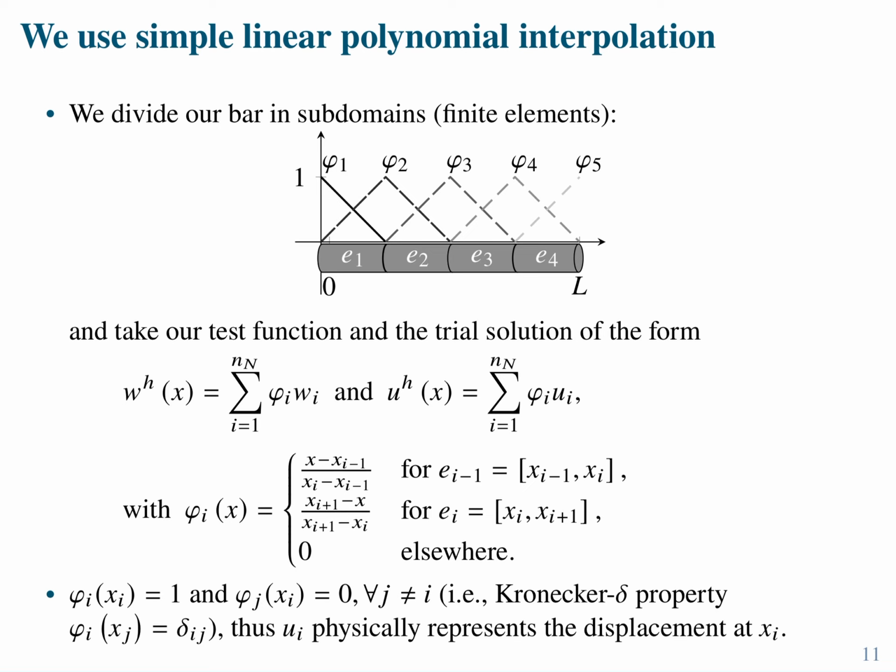You can choose functions like these ones that have the Kronecker delta property and the partition of unity property, but in general, there are many other types of formulations for which that doesn't hold. And if you want to find what is the displacement here, you're going to have to evaluate the entire expression. Okay? All right. So far, so good.